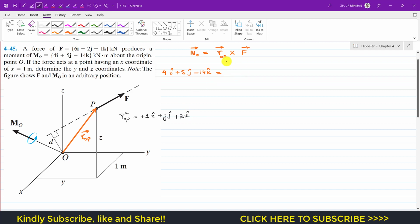Now we can write this as a determinant, so that is i, j and k, and then the components of the position vector from O to P, so that is 1, y, z, and then the force, right? The components of the force are 6, minus 2, and plus 1.